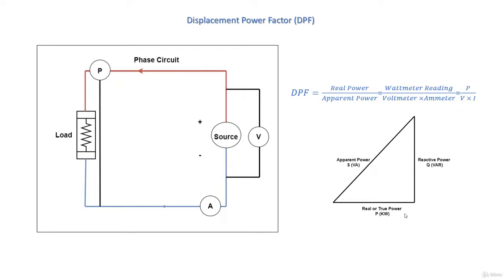However, in an unbalanced system, you could measure voltage and current at each phase separately. Also, the same goes for the power. Then get the average value to yield an average lagging or leading power factor. Note, if the power factor is 92% or 0.92, you have to oversize the inverter by 8%.